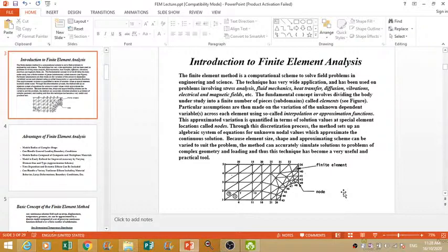Even non-CAE software like CATIA, SolidWorks and Solid Edge have a finite element module, but there you can do only a static type of analysis. In CAD software you can do just static analysis, but among CAE software, some are good modelers and some are good solvers. That we will see ahead in the next lecture.